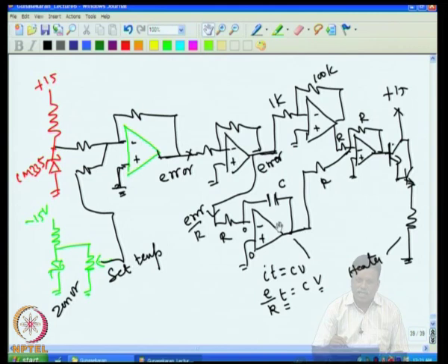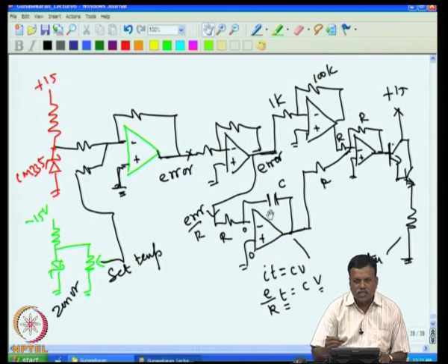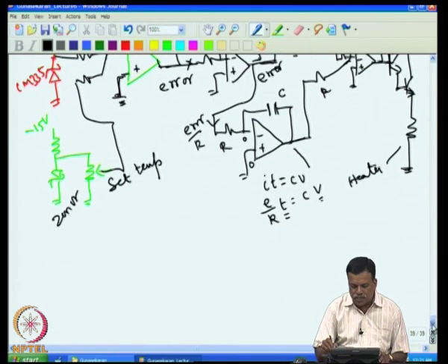But one has to correctly set the required gain and the required time constant for the integrator. Now, this is an issue to be discussed in detail, because one may wonder why, when the gain is high, the system gets into oscillation. We have to pick up this information from established control theory.